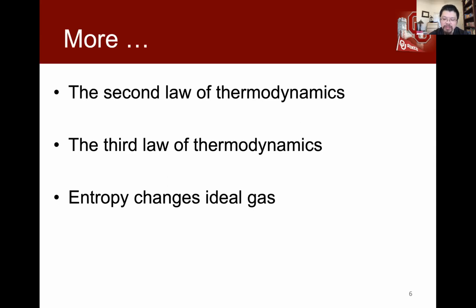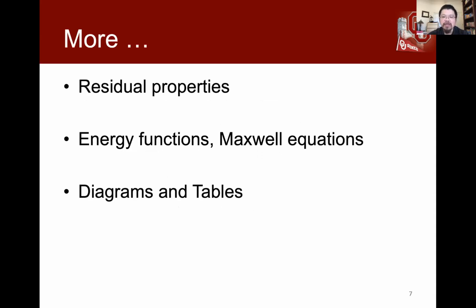So that is always from a simple toy model to some realistic discussions. That pattern has appeared again and again in our previous discussions. And then the most recent discussion of chapter 6, we had those components of, first of all, we were looking at the energy functions so that we know the internal energy, the Helmholtz energy, entropy, and Gibbs energy, what would be their corresponding two parameters, two independent parameters for each of the energy functions.